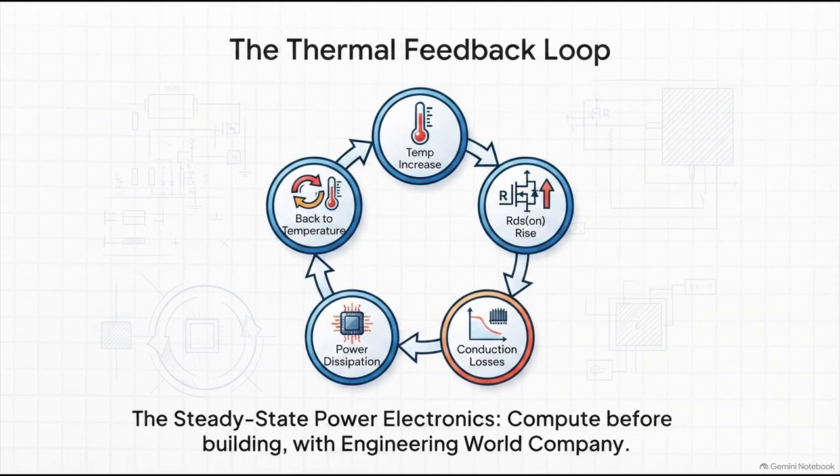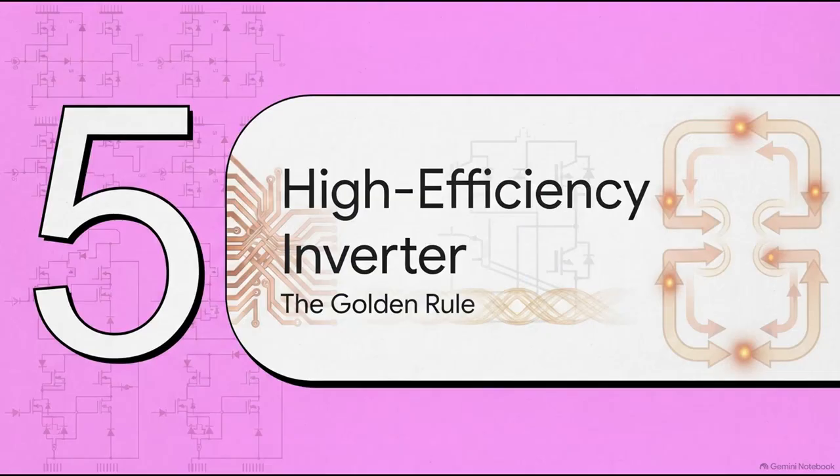First up, the ambient or operating temperature increases. Because of the inherent physical properties of the semiconductor material, this causes the RDS(on) to increase. With a higher resistance blocking the path, our conduction losses inevitably rise. Those losses are then released as energy, meaning power dissipation increases, which becomes heat. And that brings us right back to the top of the chain, further driving up the temperature, and the whole self-heating cycle repeats. Without proper heat sinks and a smart thermal layout, this loop will severely degrade the long-term reliability of your device.